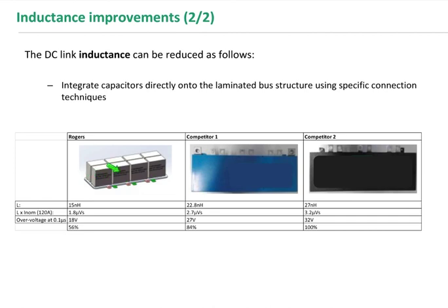As an example here, we have taken the HP2 connection, or the hybrid pack. Actually important for the designers is to know the overshoot voltage after 0.1 microseconds. Supposing you are driving your IGBTs with 120 amp, you can easily calculate it.